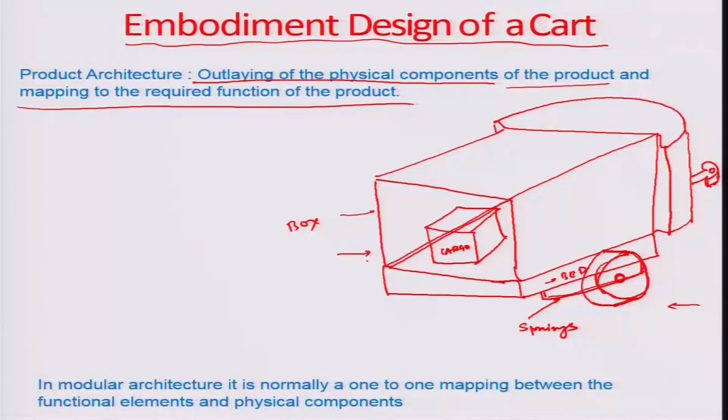So, you have a cargo here, we have a box. You can see the box right about here, there is a bed, there is a spring, there are certain wheels which would be the load bearing members, there is a fairing here just for reducing the aerodynamic drag, and then this is the hitch which will be used for pulling the cart. This hitch is attached to the end of a power provider, it could be either a tractor or some kind of small engine driven mechanism which would carry these cargoes, so a sort of cargo vehicle from the airplane to the main station or terminal or back.